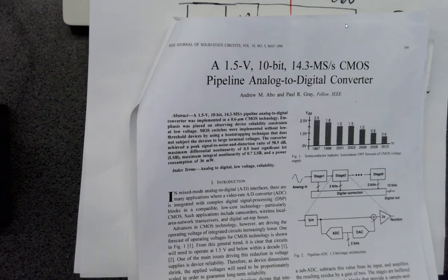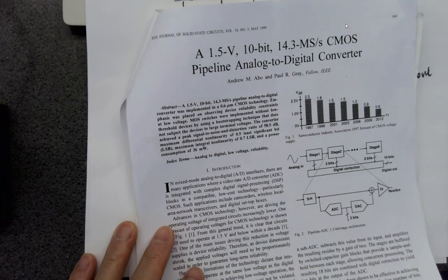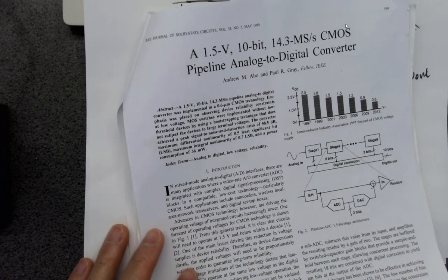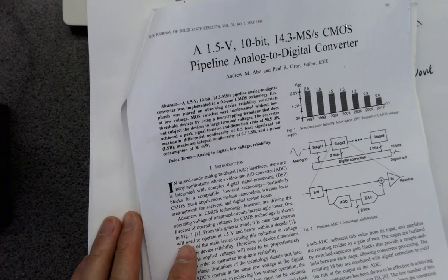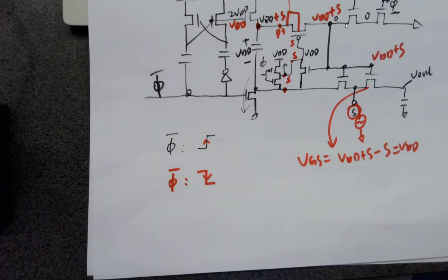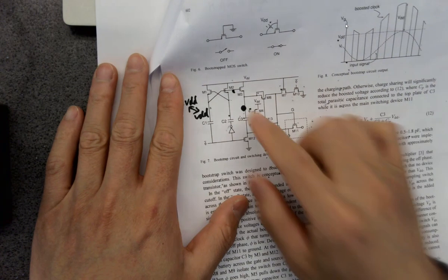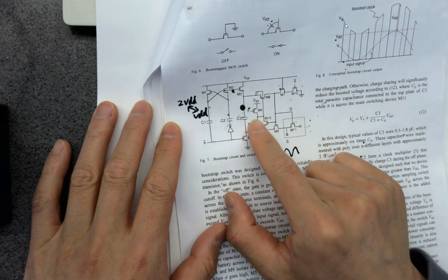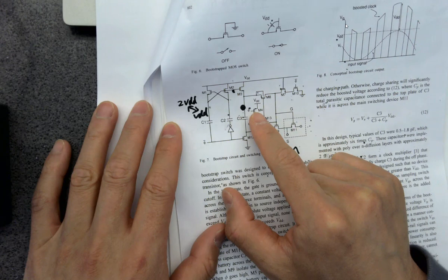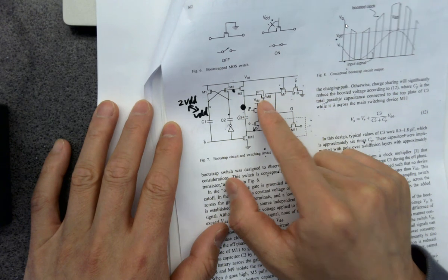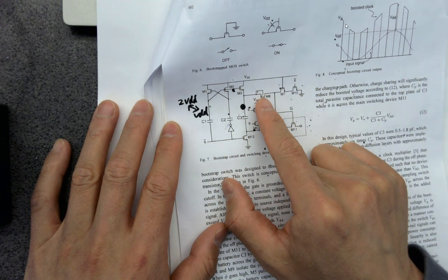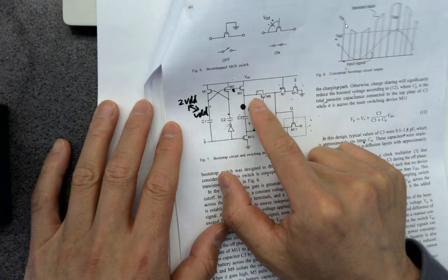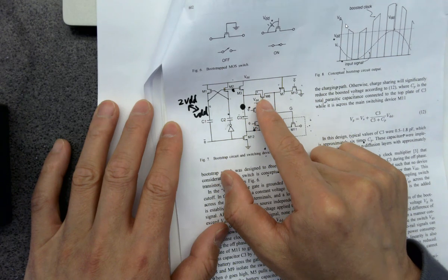And this is the sample and hold circuit being used for billions of devices, perhaps in your smartphone's camera as well. And you can see in this schematic, none of the PMOSs are being labeled differently, except this one. So you can see this one's body is shorted to the source because it's being placed in its own well.